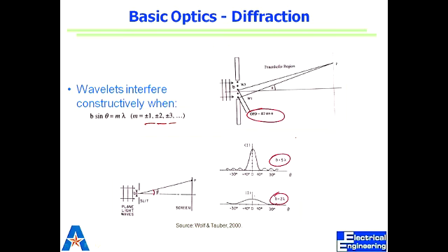But if you're thinking about photolithography or lithography, then you need those special masks to get that image. They're very expensive. Same applies to electrons also, if I'm not mistaken. Anything that travels, you can't find anything that's opaque to electrons, because e-beam lithography is mainly done by contact printing. Oh, there are some things which are opaque. So we use those stencils, masks, to do electron lithography also. We have stencils or masks for ion also. But then the question would be a different question.